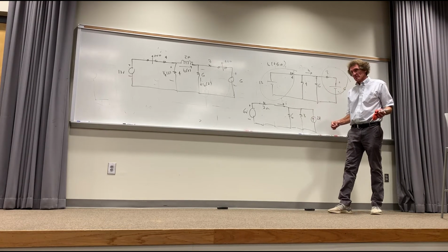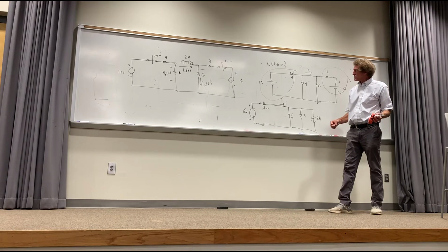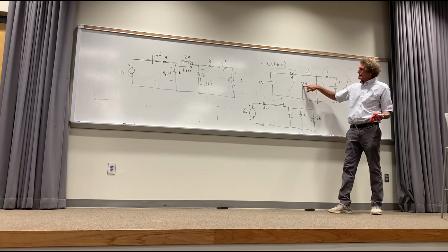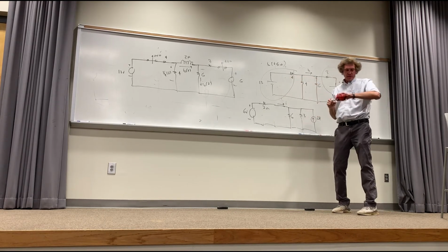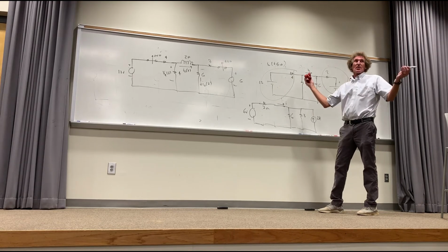There was something that I missed when I was writing up there at that top right portion. 4 and 4 in parallel, that's 2 ohms. These two were in parallel, it's 2 ohms. Right? Yes. Source transform 4, and then you have 3 amps in parallel with it.